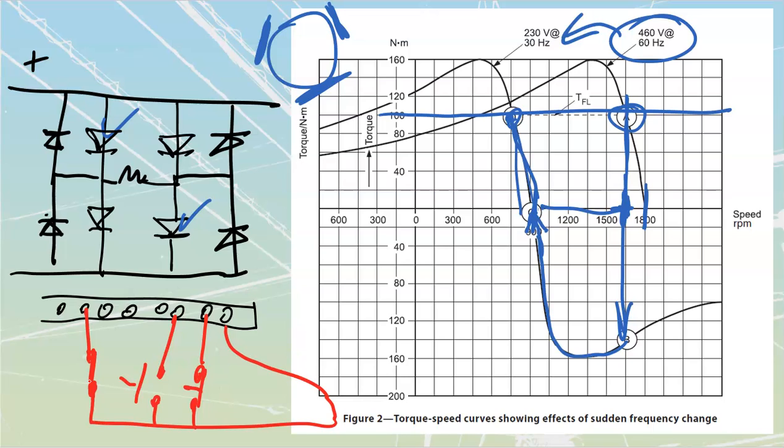And we do protect our motors by programming them into the drive itself. That whole programming of what the motor current and horsepower is very critical, because that's what my system uses to tell when we are running into an overload. It's continuously monitoring the current that we're sending out. If we've got it programmed properly, it recognizes when we've had too much current for too long, and it'll shut us down on that overload.